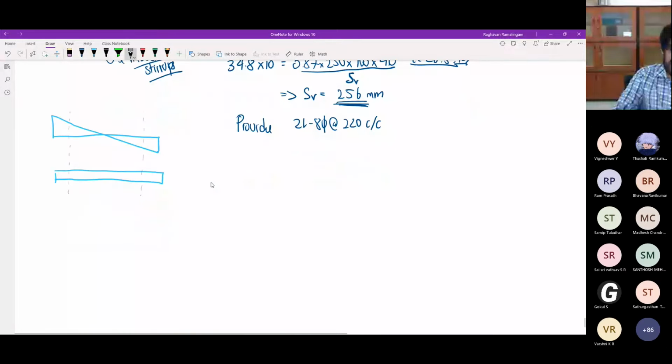I'm talking about this region of the shear force diagram. Should I maintain the same stirrups, or am I allowed to increase the spacing if I want? Since those regions come and join, I think we can. Those regions will become like joints, so that if some development bar can be used, like for a joint of beams.